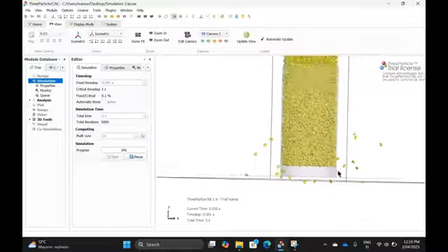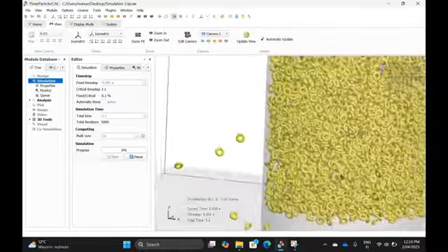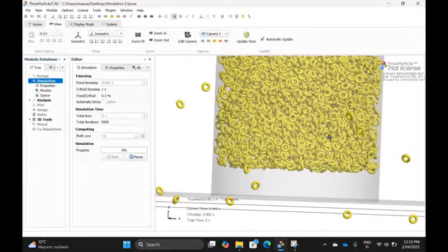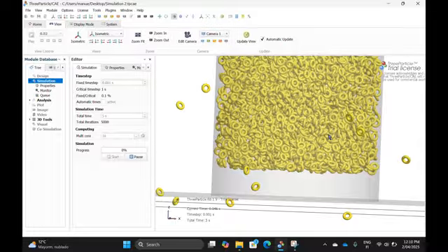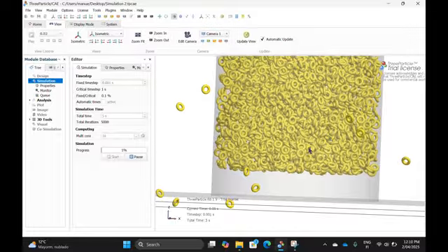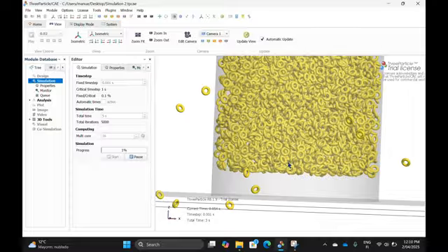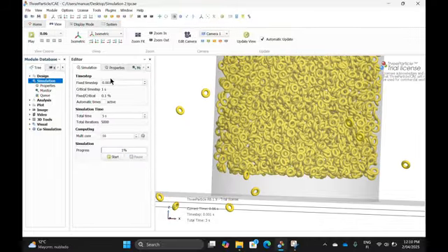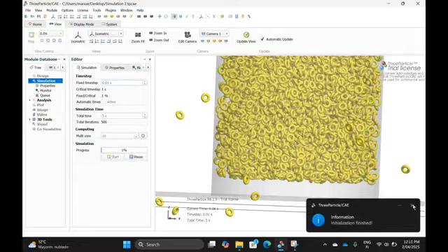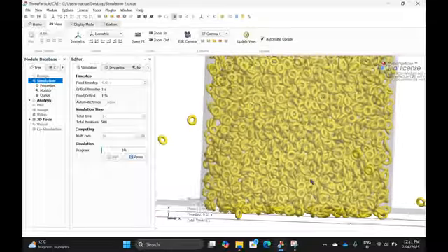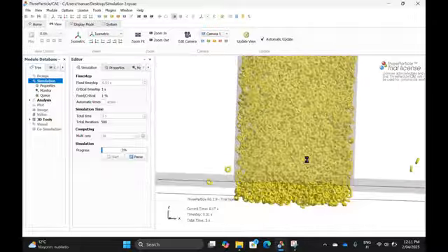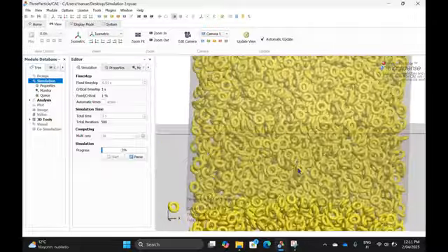If I change my shear modulus, it doesn't seem to be working. It's not moving. Now it moves. 66%. So decreasing the shear modulus gives me much more stable simulation. I have to decrease the donuts' shear modulus, and change that here, only for one of them, not for the floor. No, I didn't put an interaction. And hopefully save.